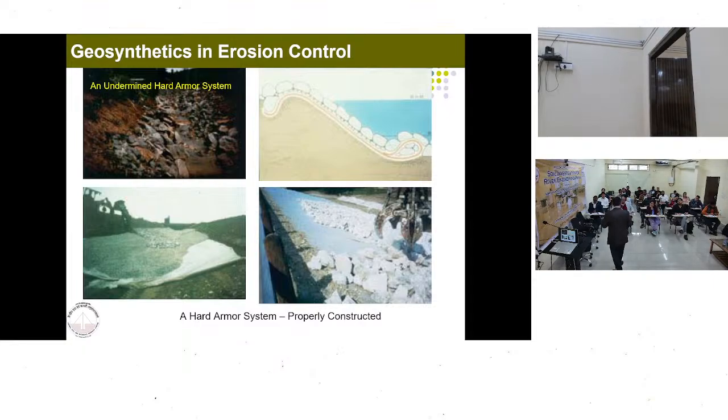This is one of the reasons being speculated. CWC is working on it, and the Farakka barrage itself is working on it; many theories are coming out. But after all deliberations, this is also thought to be one of the reasons, because ultimately flowing water requires certain sediment. That velocity carries a sediment load. That is river hydraulics. River hydraulics requires those sediments to move, and if you clean the water enough, it will erode, and that is happening.